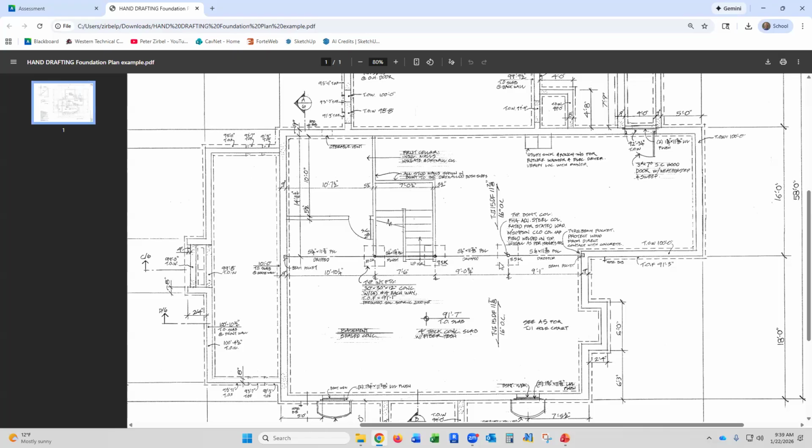And then I put the column load there because I said, typical basement column, FHA rated adjustable steel column rated for stated loads. So they could go to the Menards and say, I need a column that's going to take 9.3 or 10.2 kips. Have I talked about what a kip is yet? A kip is 1,000 pounds. Okay. So when you see something on a plan that says 9.3 K on a structural plan, that means 9,300 pounds load was going onto that column.